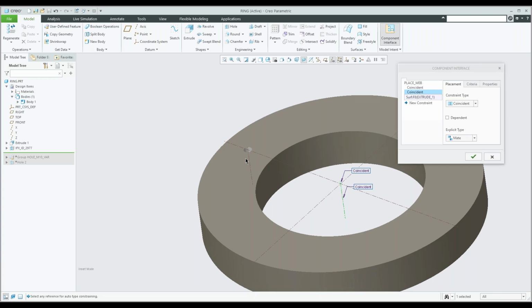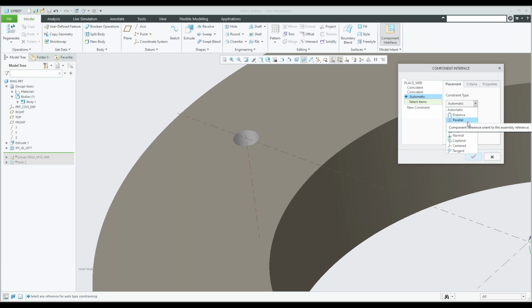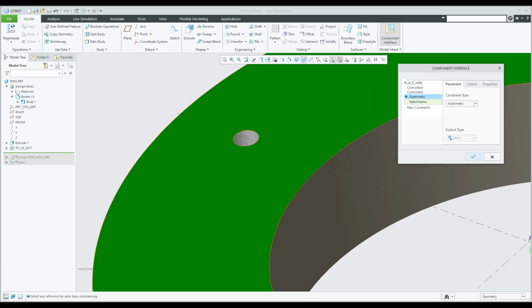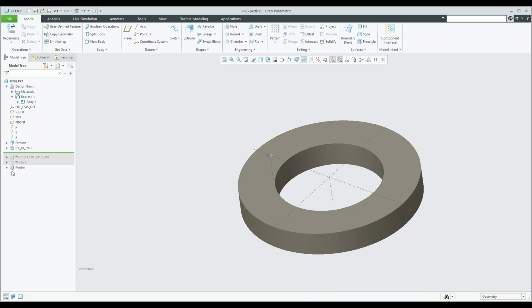You can add the hole feature to determine your orientation if you want to. So once again, you can go new. You can pick the hole if you want to, and then just give it a certain orientation, or be coincident with another reference that you have to pick. So all up to you. So I'm just going to delete that one. I'm happy with those two. I'm going to say okay. And you'll notice that these parts will have a footer here in the model tree. And you will know these guys have an interface to it, and then you can use that.